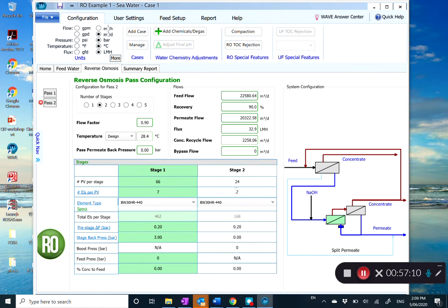We design these parameters, and we have back pressure here 3 bar only, but we can give 0, and then it disappears. So it's depending on your balance of flow rate in concentrate and permeate, so we can utilize our back pressure function.